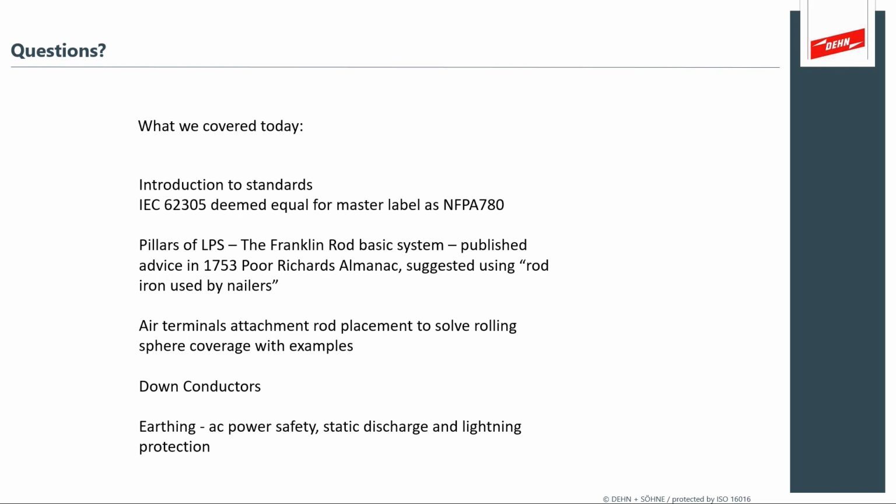The impedance of a lightning protection system, it's not necessarily a set formula that I've seen. Maybe I'll describe the measures that we take when we're installing our systems. We'll put a clamp-on meter right at the pigtail connection to the earth, and that allows us to essentially look at a resistive network upwards and downwards, and we're proving that there's a connection. To ask, is there a preferred value? You can always say, well, less than an ohm is a target value, but it really matters that all the connections look approximately the same.